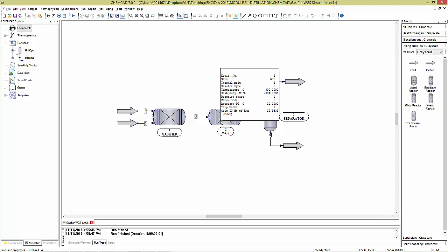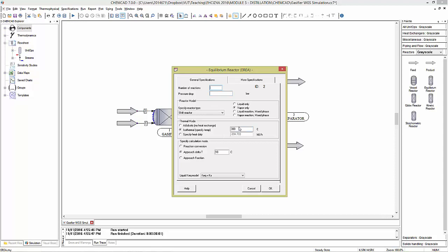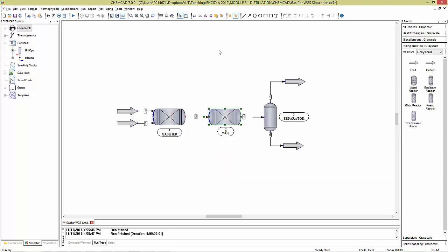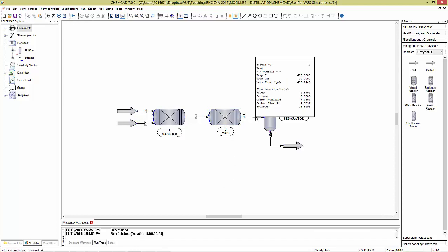Remember the direction of the water gas shift that we were dealing with, it is favored by higher temperature. So let's increase the temperature further. I would say let's go to 450. I would usually go higher so that I pass the required point and then select maybe a point in between, but at this point I will just go sequential and say let me go 450, and then let's run this, and then we can look at this.